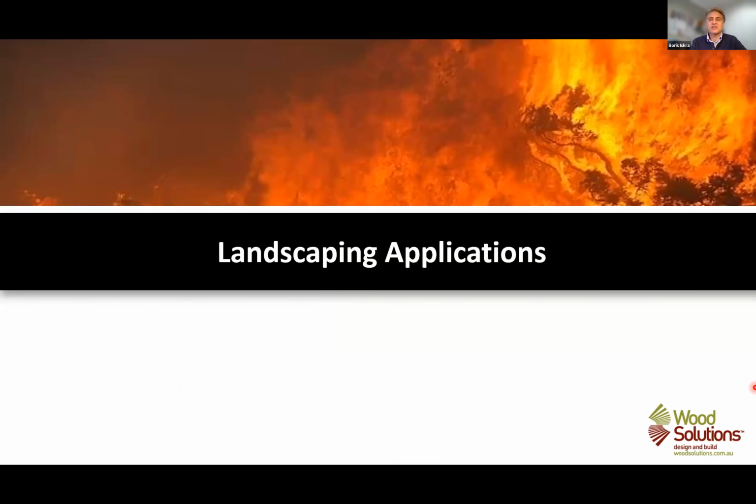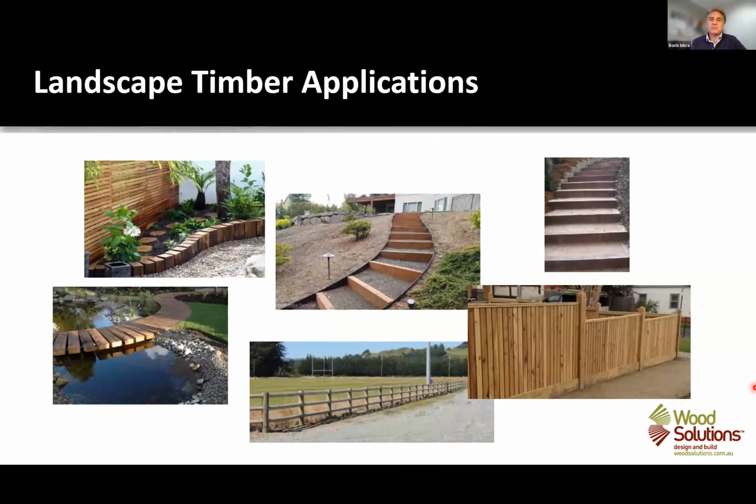Now, landscaping applications. So there's a range of applications that you'd be familiar with where timber is wanting to be used. So looking at areas around garden beds or fencing, I suppose some of the key things to try and improve the performance of structures is looking at hard surfaces around elements that then prevents the buildup of vegetation growing around pathways such as these steps. We also want to use timber across waterways and paths and fences.